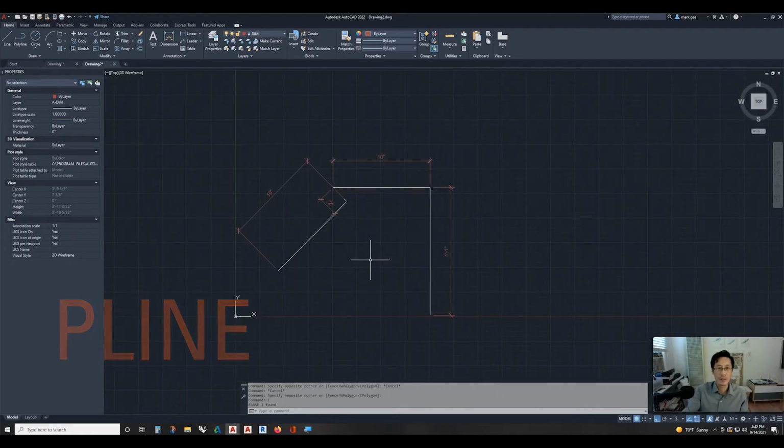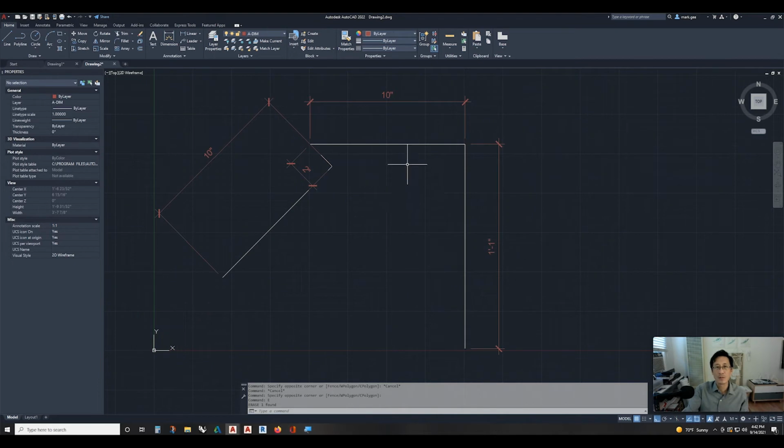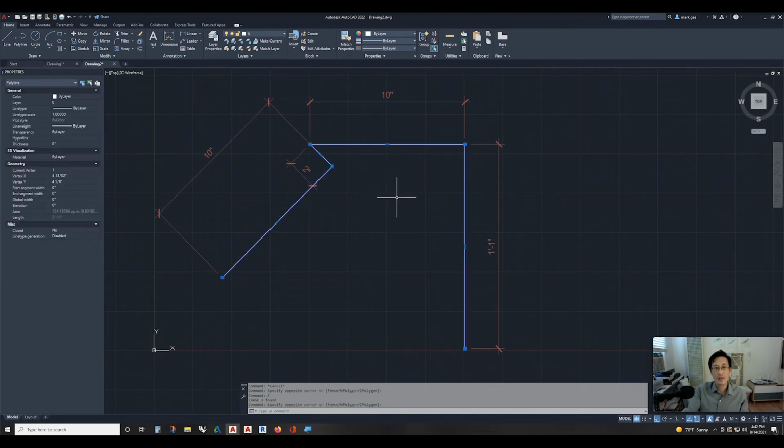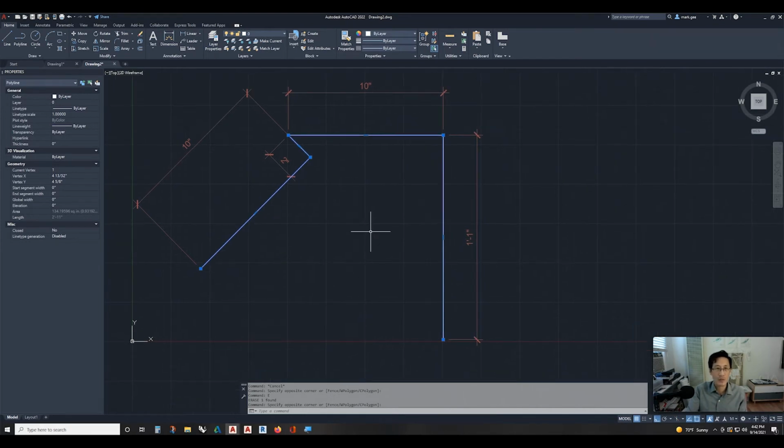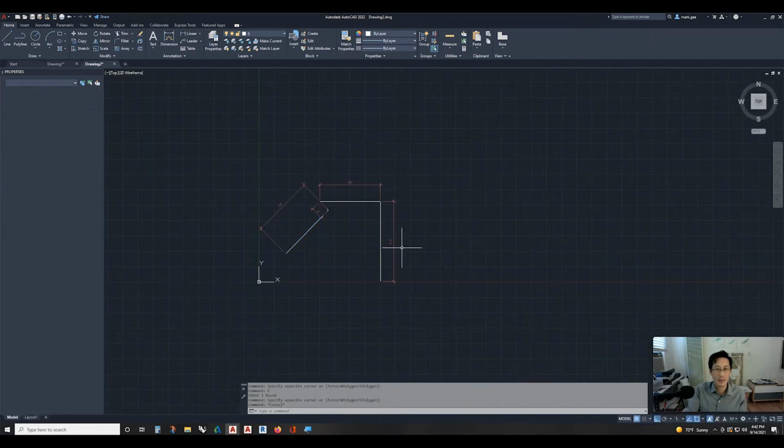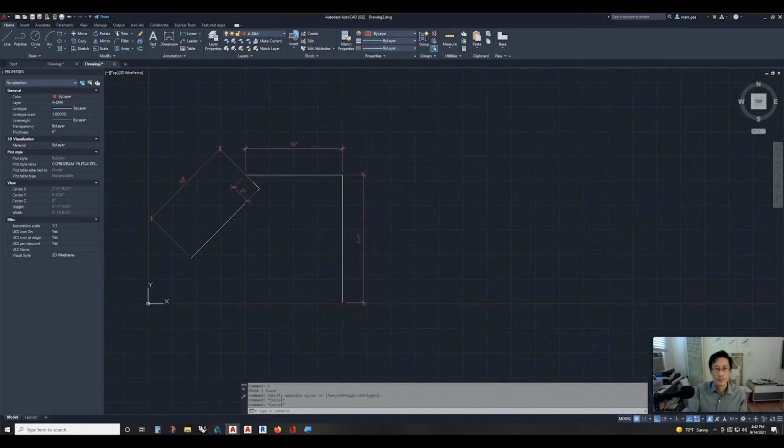A polyline is a complex object that is composed of several segments and/or arcs connected together as one object. So if we wanted to draw something like this, we'll replicate this. POLYLINE is started using the PL or PLINE command. PL is the abbreviation. We'll just start it arbitrarily someplace and follow it around the example. And so we want to draw at the same angle here. Those are 45 degrees that I had in this example.